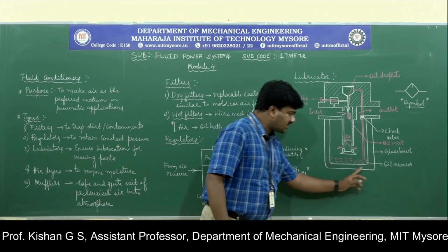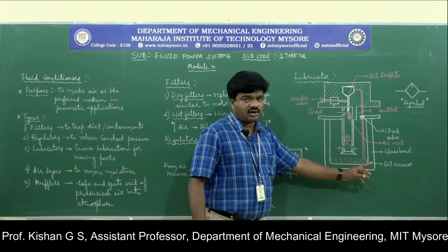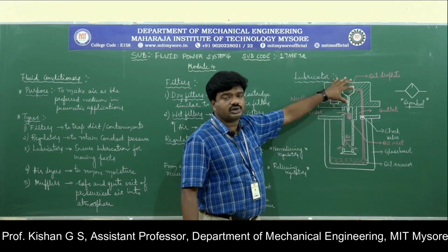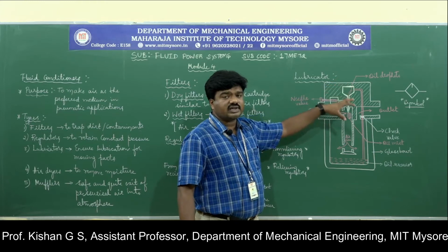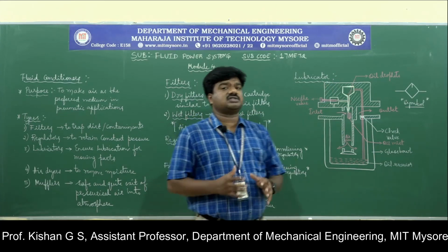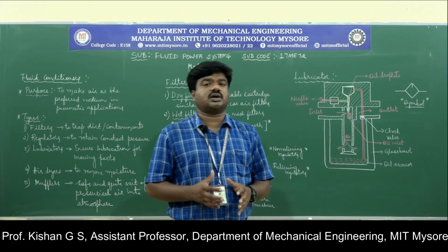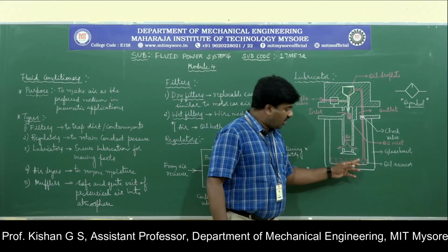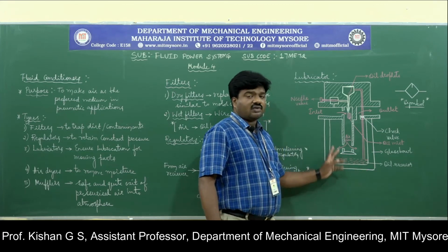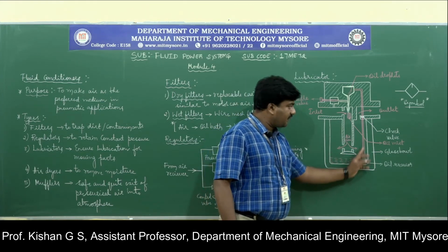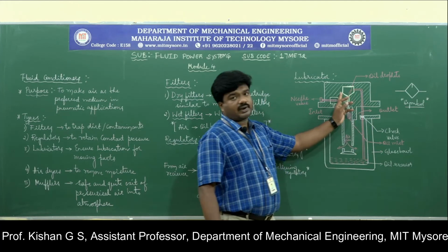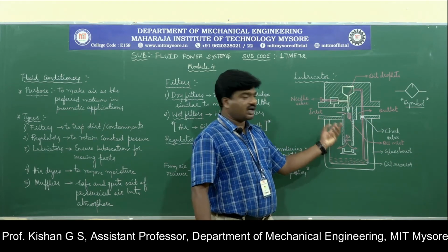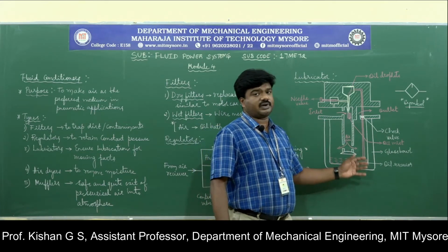The oil which is present inside the oil reservoir, as well as the area where the upper portion is provided, there will always be the concept of differences in pressure and density that comes into the picture. Due to the variation in pressure, the oil at the reservoir will be made to pass through the capillary tube into the top head portion, wherein it gets collected in the form of droplets. This is due to the pressure difference.